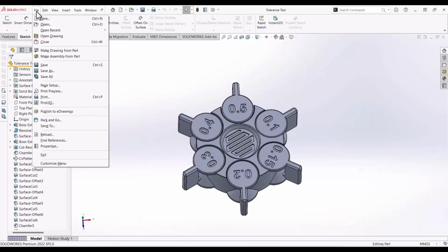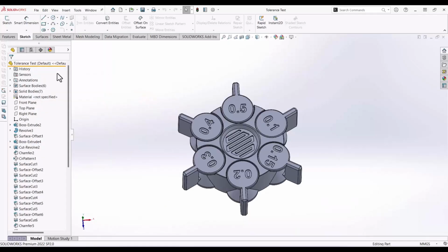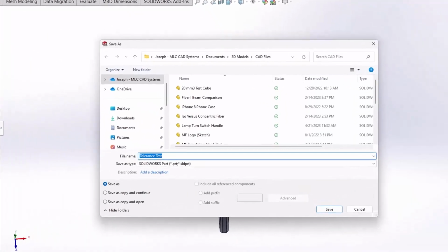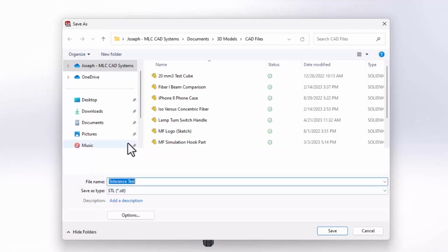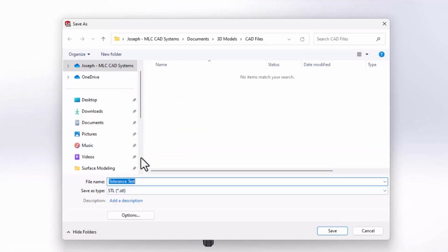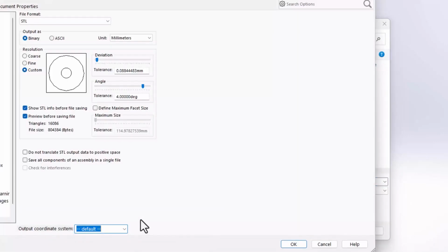And when you go to save the STL, you can open an options window on most CAD softwares. And from there, you can modify chordal tolerance and angular tolerance. And minimal side length is kind of an optional thing. The chordal and the angular are the most critical. And you just want to make sure that your file size is less than 20 megabytes.